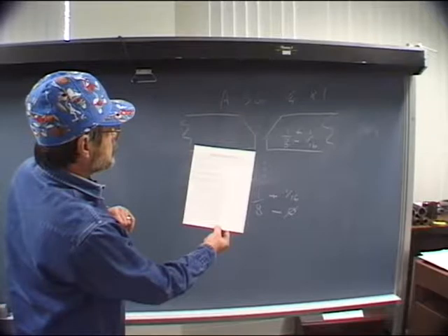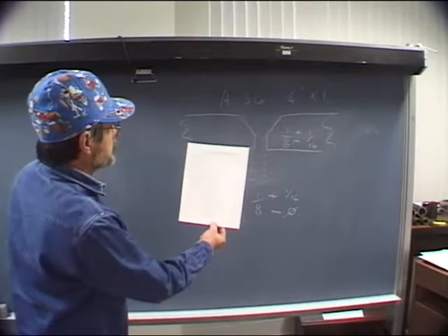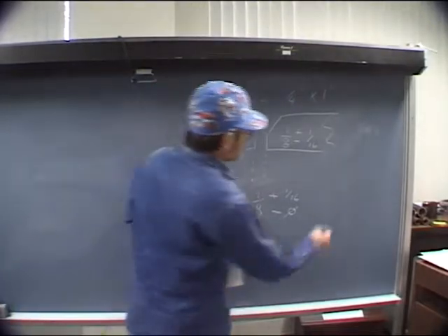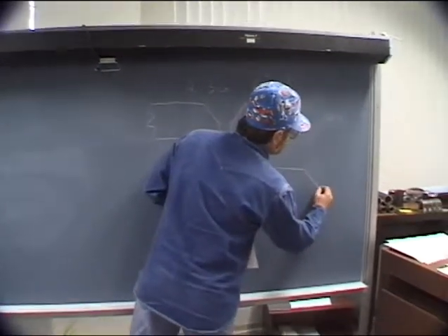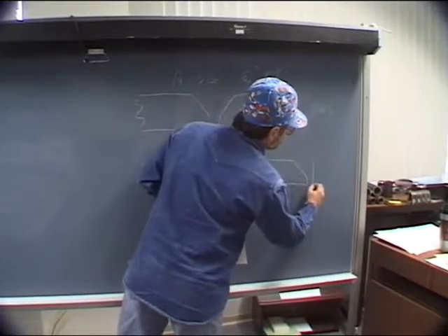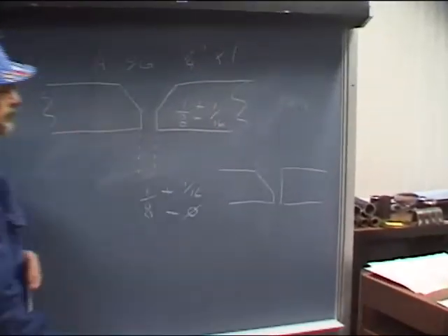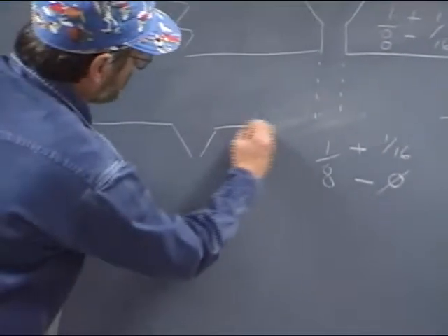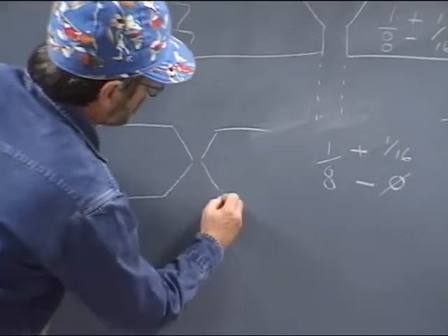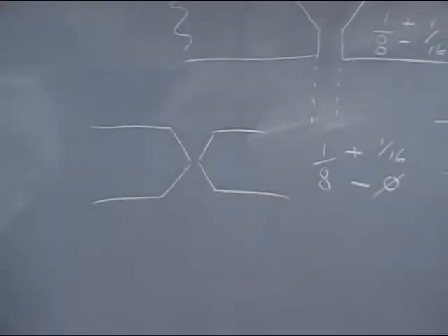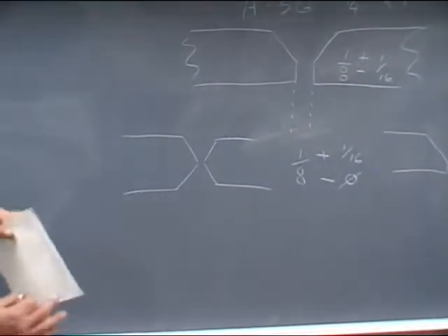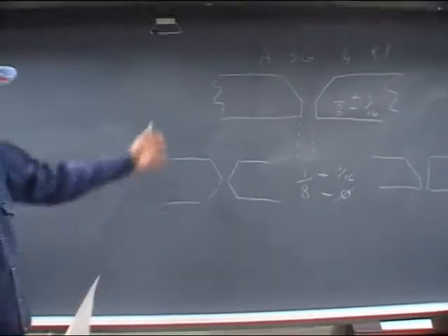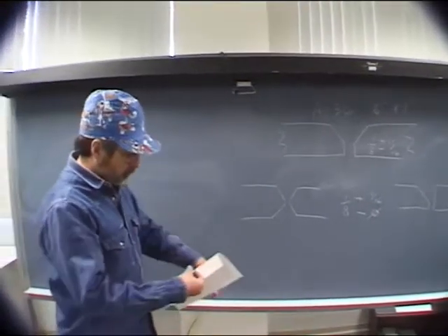The rest of that's pretty self-explanatory, and these welding procedures can apply to more than one joint. For example, we might want to apply it to a single V joint, like so. That's perfectly okay. You can apply it to that, or you might want to apply it to a double V. That's perfectly okay. We've already established that the procedure works, as long as you're using the same type of material. And so it gives you more leeway.